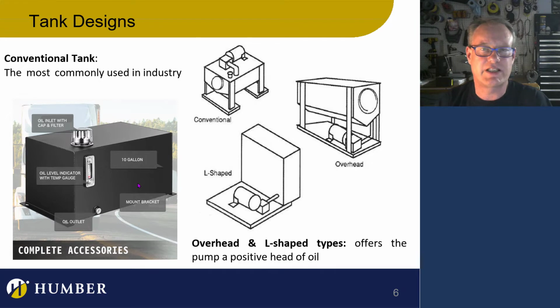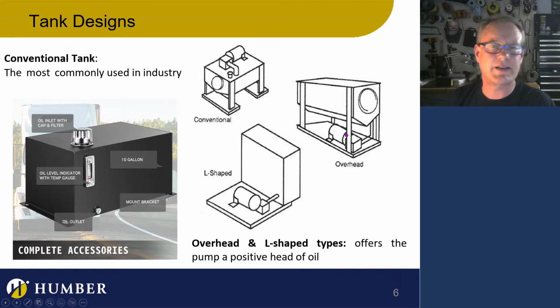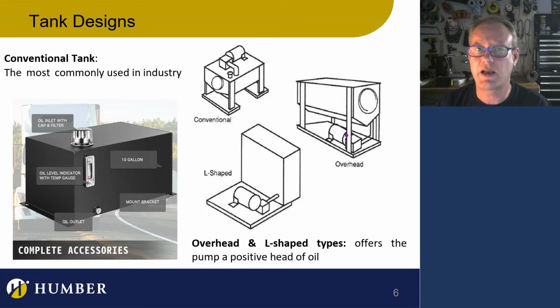There's a pretty standard or conventional tank configuration where you're going to see the motor, the prime mover, and the pump right on top of the tank. But there are other ones as well. They have a benefit: with the ones below the tank or beside it at the same base as the tank, the pump doesn't have to suck the fluid in.